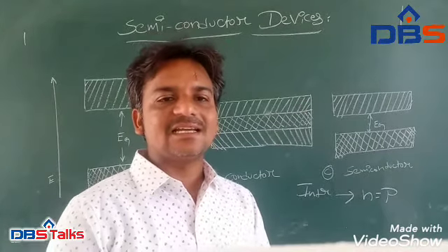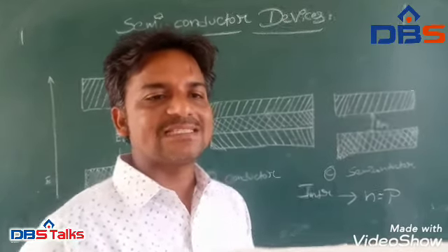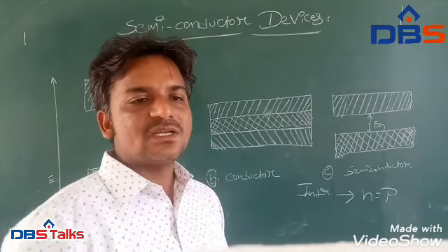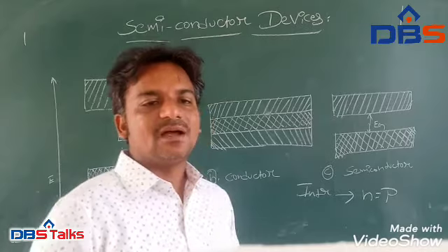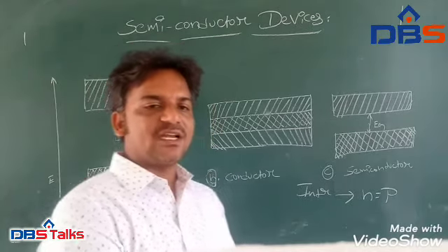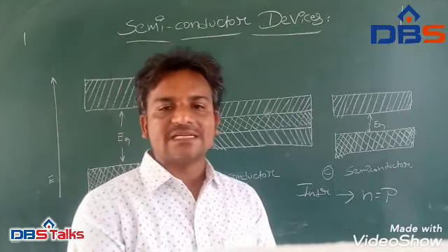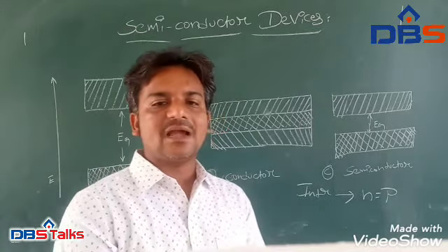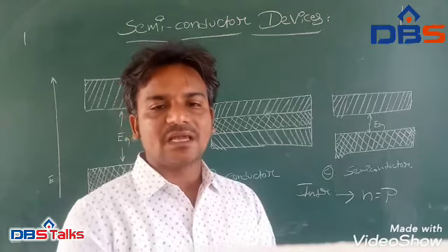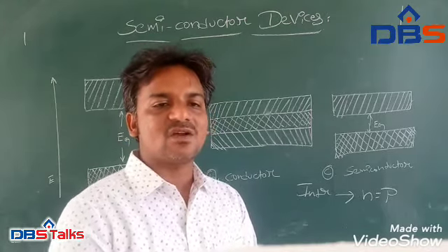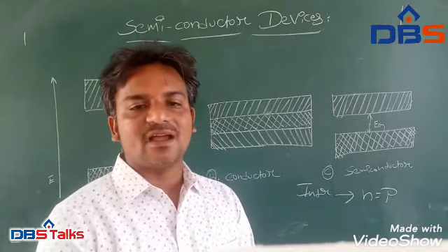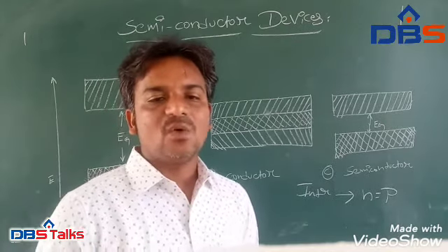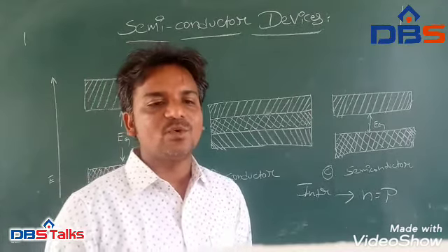The term intrinsic here distinguishes between the properties of pure intrinsic silicon and the different properties of doped N-type or P-type semiconductors. In this intrinsic semiconductor, we have electron-hole pair generation. In an intrinsic semiconductor such as silicon at temperatures above absolute zero, some electrons are excited across the band gap into the conduction band, which can support current flow. When an electron in pure silicon crosses the gap, it leaves behind an electron vacancy or hole in the regular silicon. Under the influence of an external voltage, both the electron and the hole can move across the material.